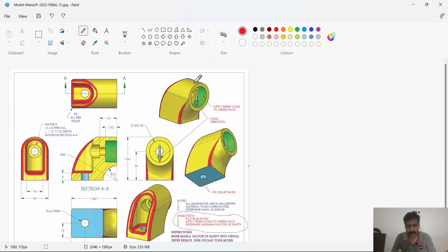We use the static stress simulation when we need to know about the design and about the material under the applied load. If the material is going to fail, if it is a structural member, then we have to look if there is yielding happening, because after the yielding the design will fail for the structural member. So that's what we are going to see in this study.